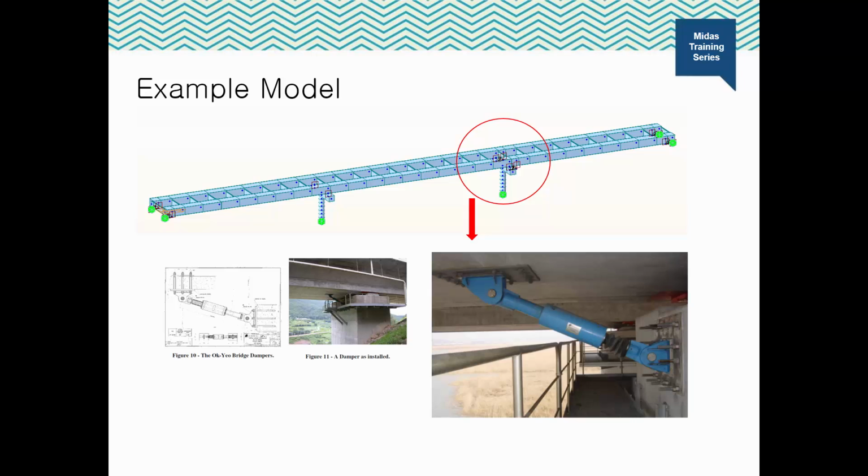For boundary nonlinear time history analysis, should we select the direct integration or the modal superposition method? A comparison will be made for all such methods and the difference in results and accuracy will be presented. For the purpose of comparison, we will use a bridge model.